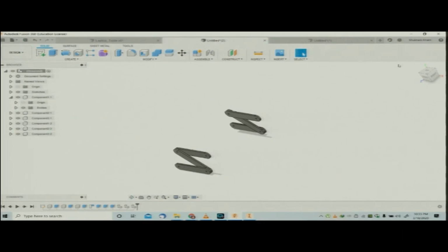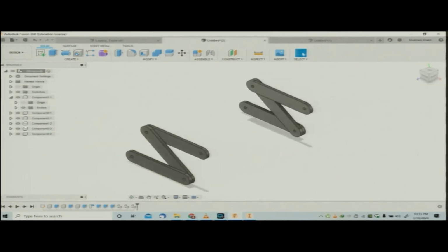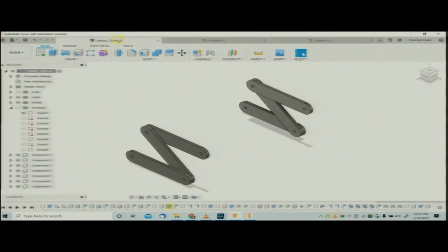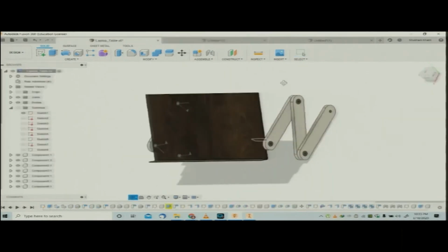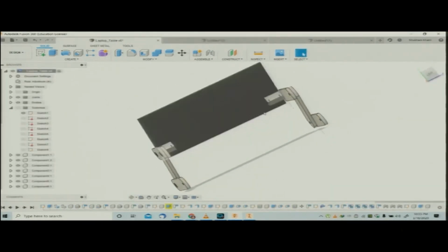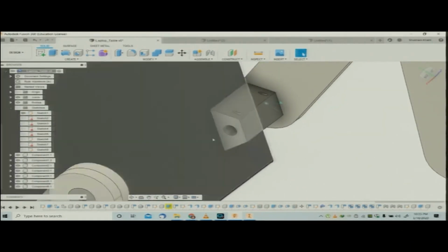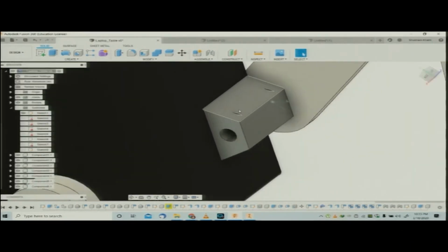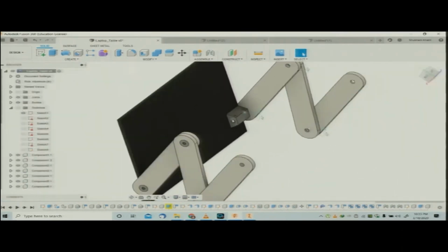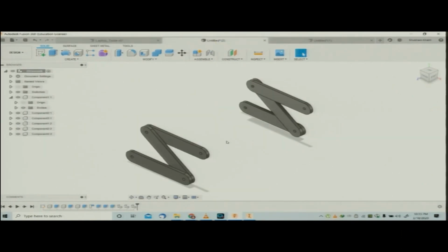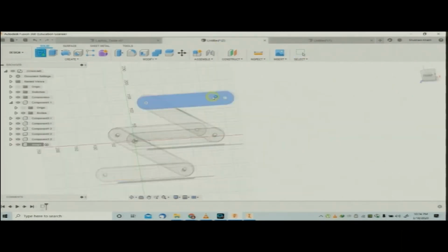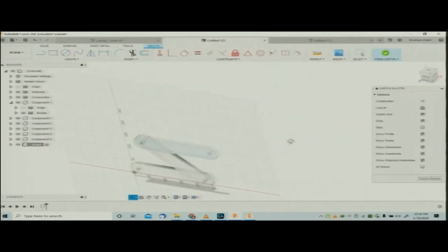Next thing that I will design here is my sheet metal component. The top face has to be designed. Before that, I have to design a hinge here. This hinge will be fixed below the sheet metal component. This hinge support, I would say, for sheet metal, is to be created. I will just make a simple rectangular hinge here. So, first we need to make a sketch here.